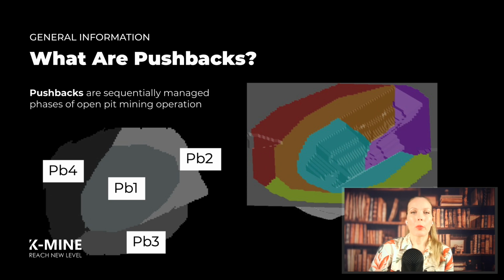Pushbacks allow for management of the intensity of mining across different areas, coordinating efforts over time. A pushback represents a controlled phase of pit development, ideally made up of unique adjacent volumes that can be mined with the current equipment while respecting practical geometric limits. Generally, pushbacks are mined sequentially, and once overburden is removed, equipment shifts to begin the stripping in another area, ensuring timely mineral extraction.